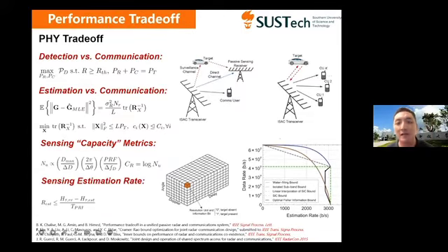They have proposed a passive radar and communication joint system, with orthogonal resource allocation, one for radar and one for communication. So the power is split into the radar power and the communication signal power. They wish to optimally allocate power between radar and communication such that we can maximize the detection probability subject to some communication rate threshold. So this is some analysis on detection versus communication based on a passive ISAC transceiver, a passive sensing receiver.